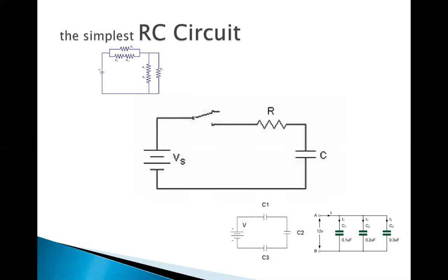remain on the capacitor. So if you take a capacitor out of a cabinet in the lab, be careful, because although it's not connected to a power supply, it can have charge and can have electric voltage. Be careful when you touch that capacitor.